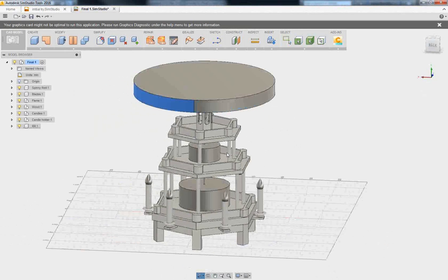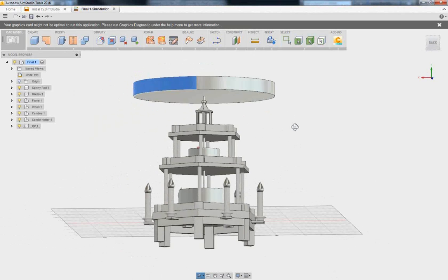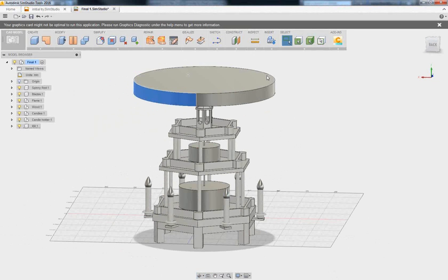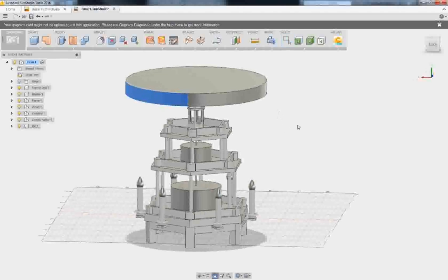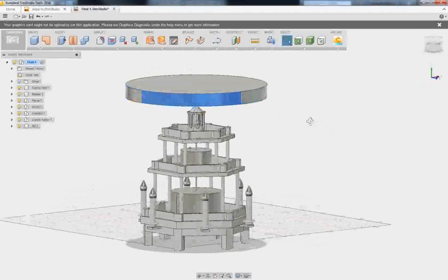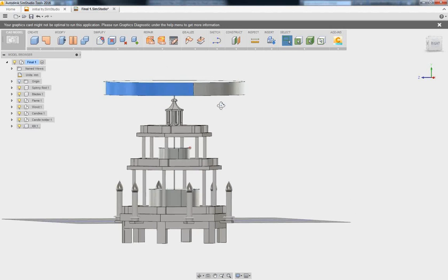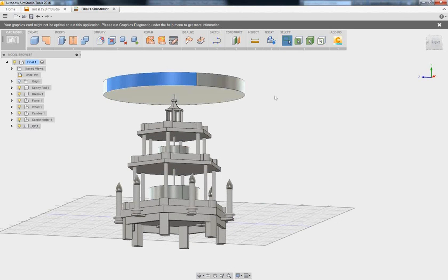Here's another one. My rotating region, I don't know why this happened, and I think it was just because I grabbed a surface and offset it, and then I tried to pull a couple of different edges to generate this top piece. And you can see that it broke it into 4 pieces. So I was getting a solver exited unexpectedly because of that. So I ended up going back to my geometry. This isn't the final one that I ran with, and I had basically deleted all of the top of this and put in a new cylinder and reattached everything.